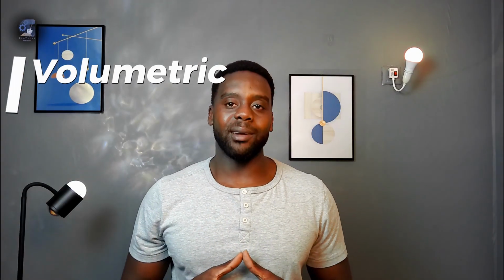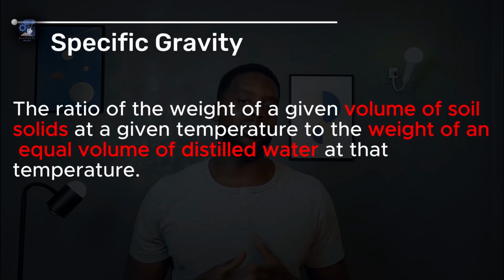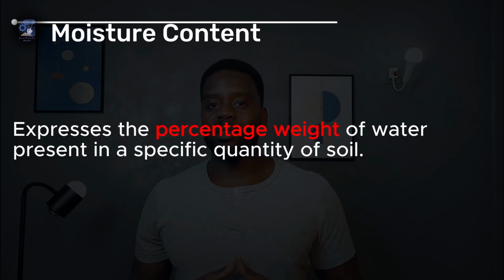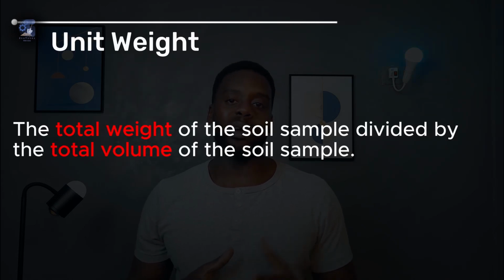As for the volumetric characteristics, the properties of most interest in this group for pavement design and construction are the specific gravity of soil solids, which is the ratio of the weight of a given volume of soil solids at a given temperature to the weight of an equal volume of distilled water at that same temperature. The moisture content, which is expressed as the amount of water present in a quantity of soil, and the unit weight, which is the total weight divided by the total volume of the soil sample.